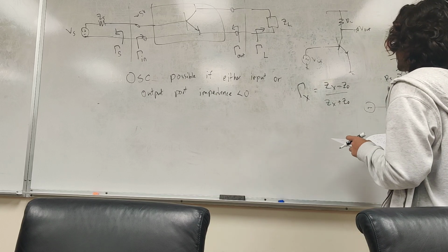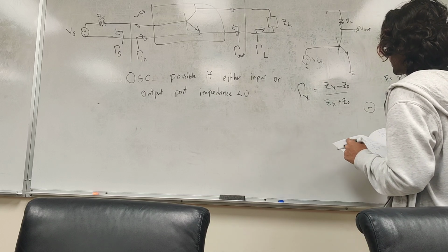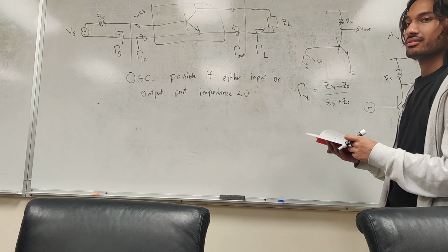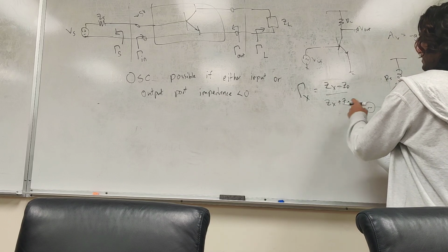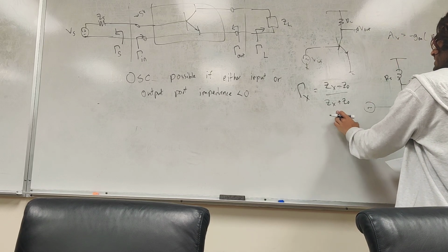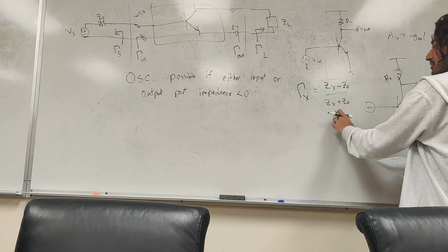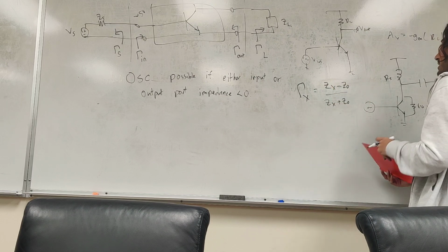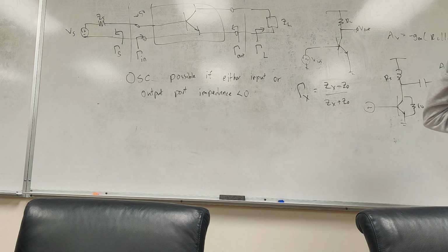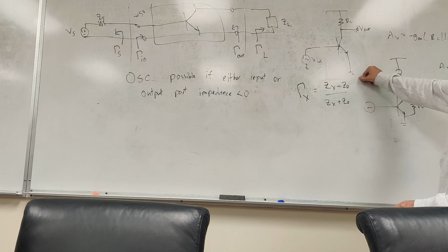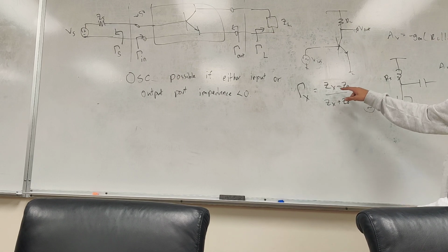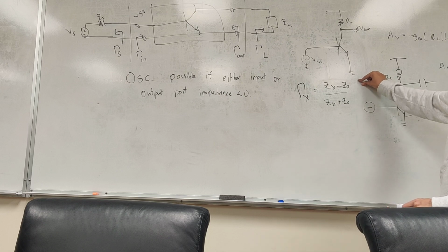And what we're going to see is that it has to have a negative impedance, right? This magnitude is greater than 1 because this denominator is always going to be larger than the top. Z naught is 50, this is like 60, then we get 10 over 110. If Zx has a negative component, that becomes a negative at the top.